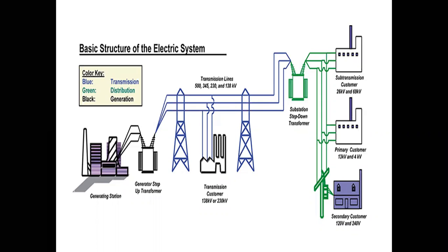So here, from the generation level, electricity will be generated depending upon whatever generating station you use. You can use solar, hydro, nuclear, thermal, geothermal. All the generating stations can generate electricity. How? In all the generating stations, one form of energy is converted into electrical energy. As we discussed in our previous lecture, this generated electricity at a certain level of voltage will be stepped up with the help of a step up transformer.